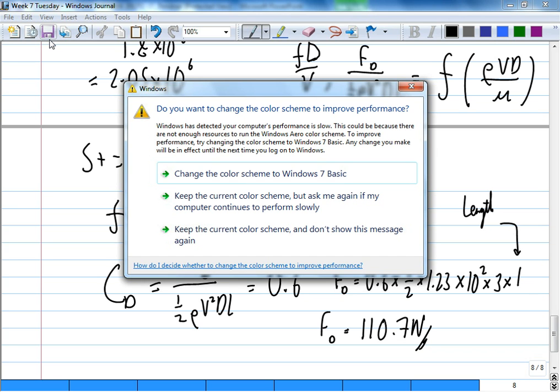More recently, a lot of the ships have a bulb here, a bulbous bow. You've seen it before? Some have seen, some haven't. I'll show later. This one actually helps to cut through the waves and reduce the drag by quite a lot, and saves a lot of petrol or diesel. Mainly the big ships have it. The bow bulb.